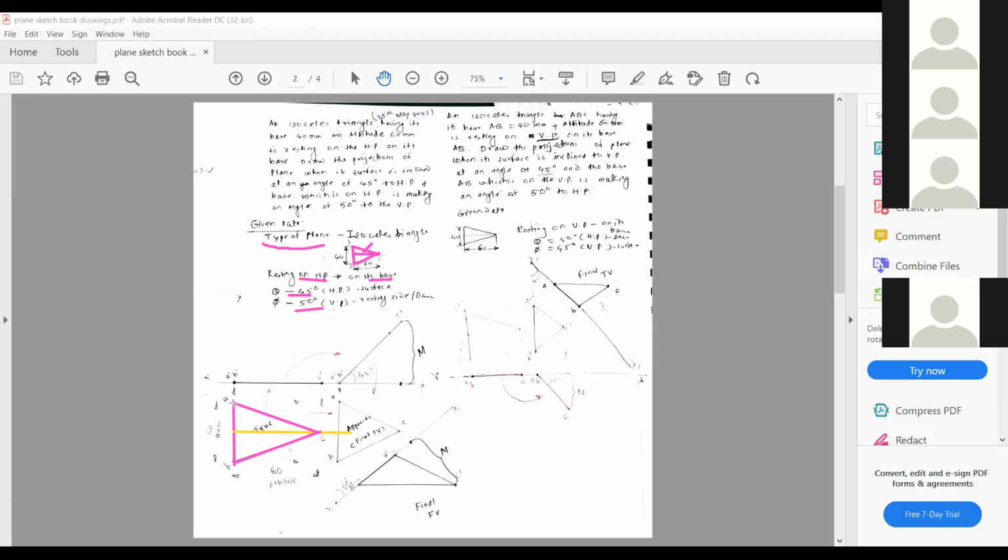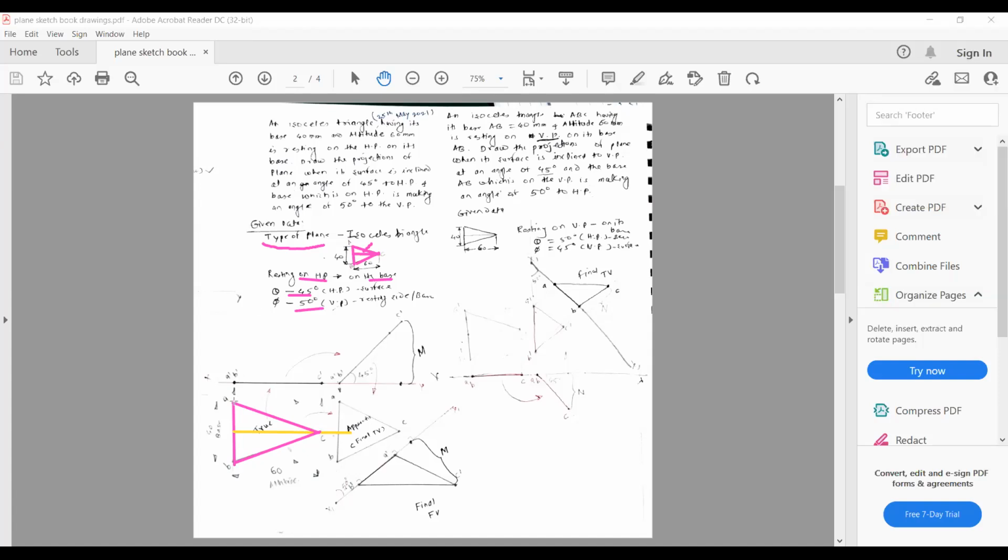Then take the projection from both the points. Take the projection vertically till it touches the XY line. Then on this line you will get the 2 points.